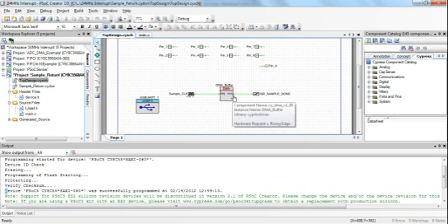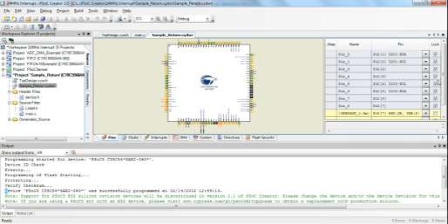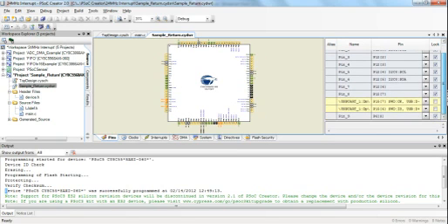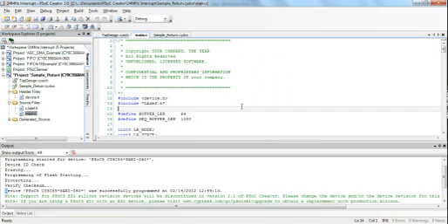Once that is done 1,000 times, meaning 1,000 bytes have been moved, a signal is sent to trigger the ISR, and the ISR will come out of that and tell the PSoC to now send the data back up to the PC. If we look at the pins, basically the 12 input pins are all mapped to the 12 special input-output pins. Pin 9 is an LED that actually didn't get used in this, and USB UART is set to the USB pins. If we go to the main file, we can see a couple things.